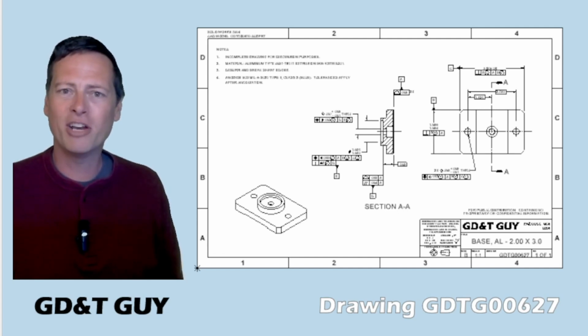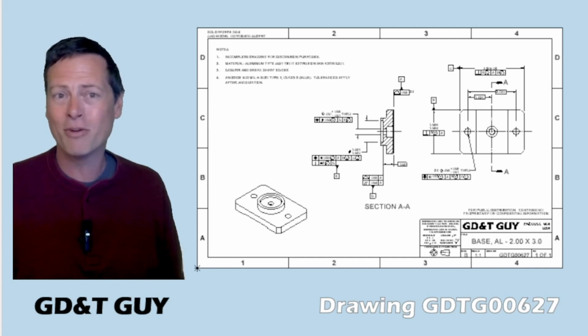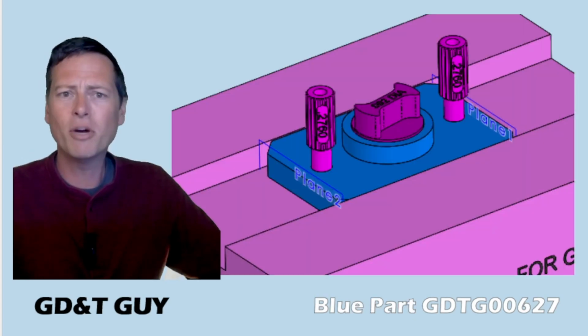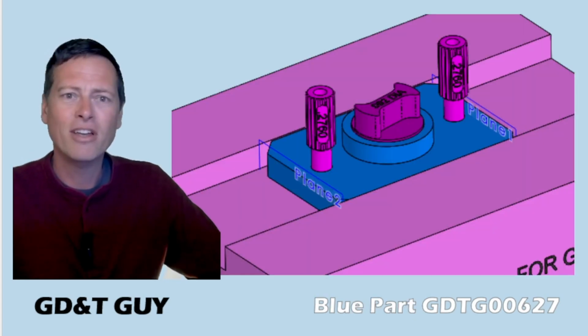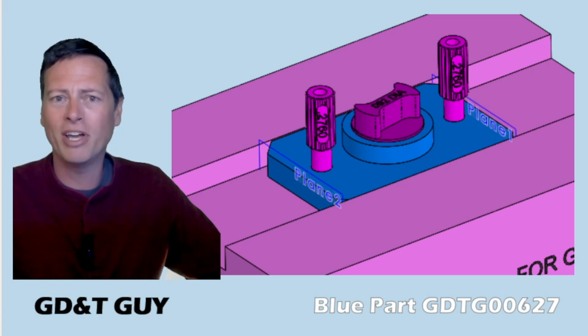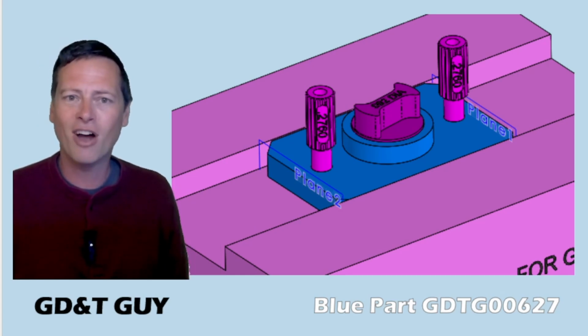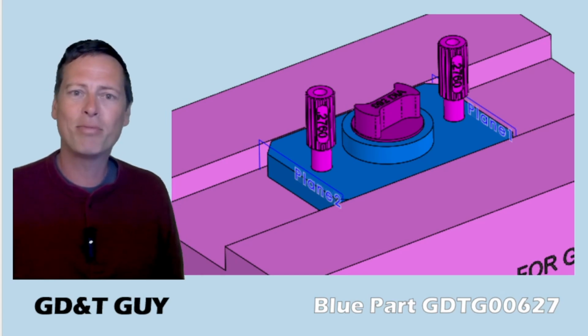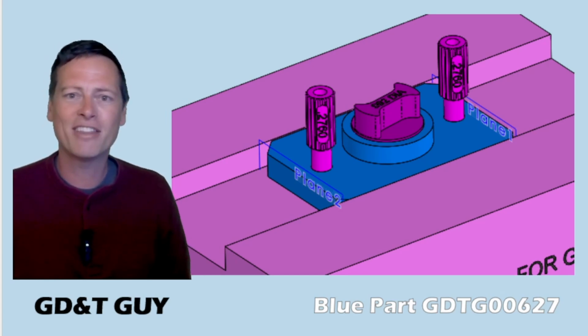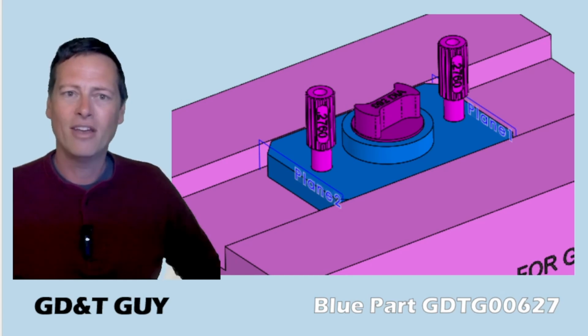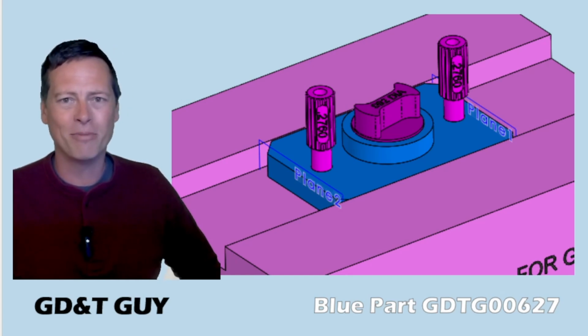Is LMB going to be viewed as a little over the top for a part like this, even for people who understand what it means? I don't know. Let's go back to the inspection gauge. How are we going to know where these planes are, and if the edges are inside of them? It's probably going to require a CMM or something along that line, right? So we install our gauge elements, and then we probe these ends to check that they are outside of the boundaries. Okay, well that just seems a little backward to me.